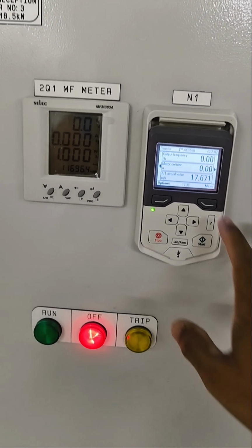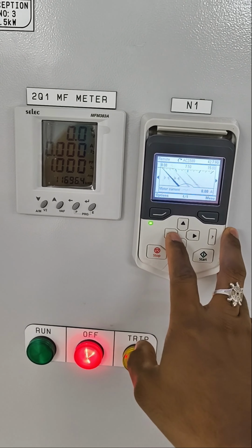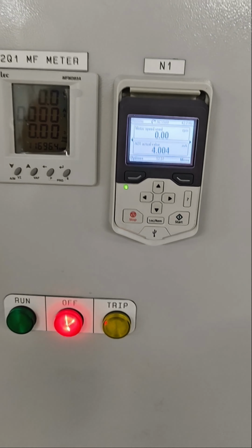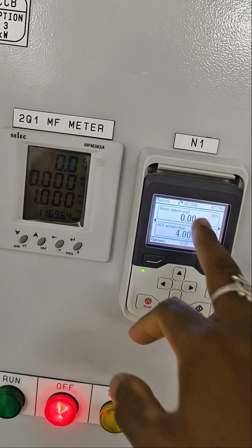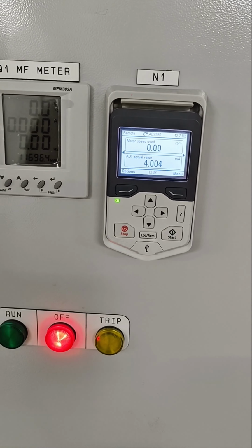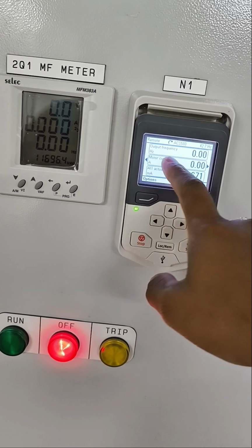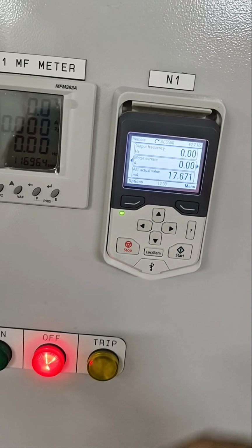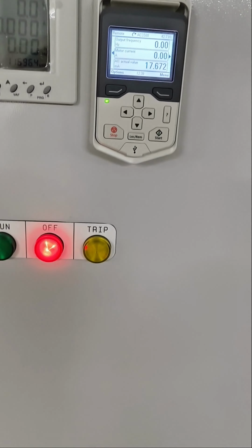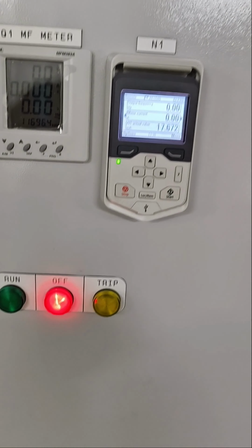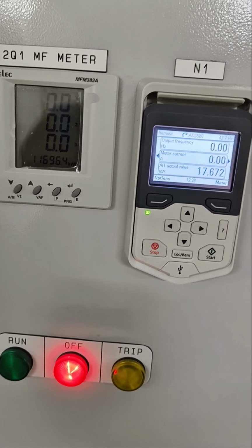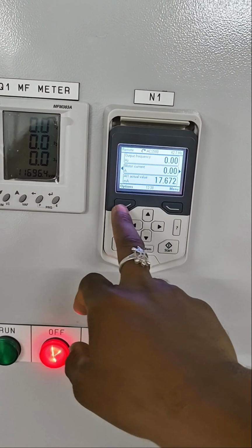You can see the real-time values of the motor. Now as you can see, it's in the off condition. So now let's get started on how to find out the run hours by using this HMI. Here you can see the output frequency of the motor, how much current it's consuming in amperes, and the scaling, meaning the input analog current for controlling the speed of the motor. Okay, let's get started with the parameters.